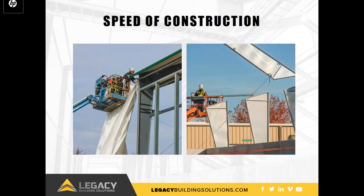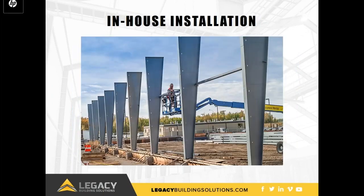As we mentioned, speed of construction is an important factor in the installation. Finishing the building construction sooner means dollars saved on construction costs, plus dollars earned for faster occupancy and use of the building. Speed of install is one of the areas that fabric structures outrank steel. Large sheets of fabric are pulled and attached into place about 3 times faster than steel panels are installed.